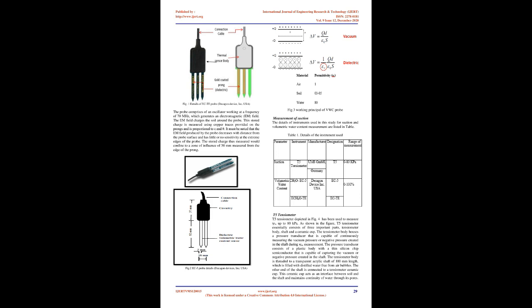3. Working principle. The basic principle behind the working of the probe is that the dielectric permittivity, ε, of the soil medium changes with its water content, as shown in Fig. 3. ε is dependent on the capacitance property of the soil mass. The probes measure the capacitance property and give the output in millivolts, mV.